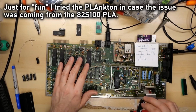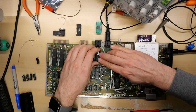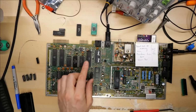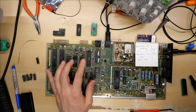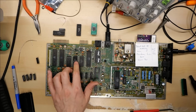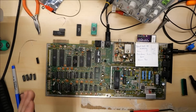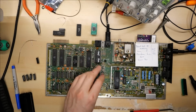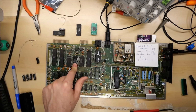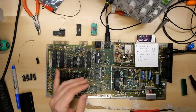At this point, I am suspecting that the CPU is the problem. The PLA we know we can rule out because I'm already pretty sure this is a good one, this A2S100 one. And then the Plankton here, well, obviously that one works too. So what the PLA does, just in case you're not familiar, is it selects the different chips. So when you're trying to access the kernel ROM, it selects that chip, so it talks on the data bus, or the BASIC ROM, and the video chip, and the cartridge port, and all that kind of stuff. So if the PLA is bad, that is why this machine wasn't working originally, because it was always keeping the kernel ROM selected all the time, even when it shouldn't have been. So that was just stomping all over the other chips and nothing could run.